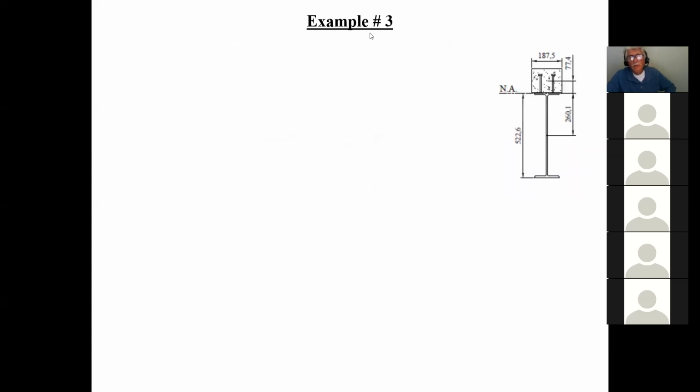So here I have, like, guys, make yourself sketches and be clear on your sketches so that you can do these calculations. Don't do them in your head. It's the easiest way to make mistakes. So the first thing I do is, this is the centroid, okay? And therefore I calculate the distance from there to there, and then I calculate the distance from there to there. My neutral axis is all the way up here. That's what we calculated before. Therefore, that's the value, that's my D for the steel.